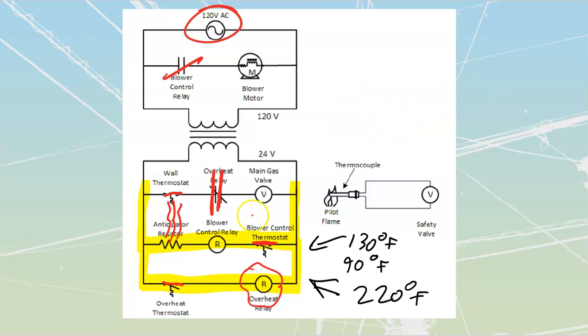What we will see is that it does not shut off our blower fan. So our blower fan is still going to be able to try to clear that heat. We get dangerous amounts of heat, 220 degrees inside there. So it makes sense that we would still want to try and clear that out. This thermostat over here will not open until we drop below the 90 degrees Fahrenheit that I'm going to have. As we start dropping back down, eventually this thing will drop back open. It depowers that. At that point, this thing would be cleared to close up again.